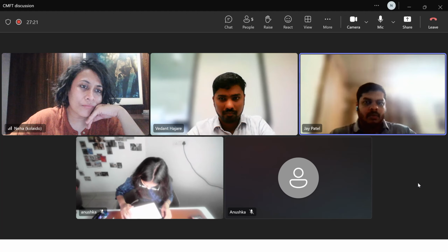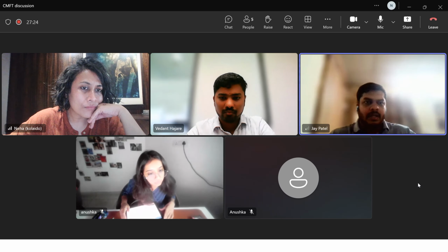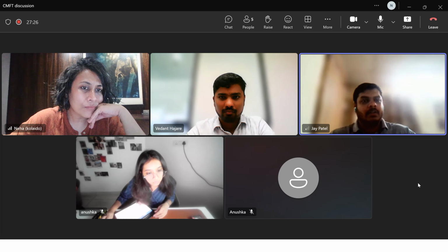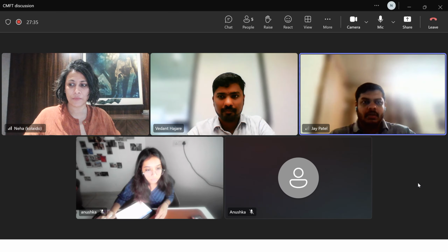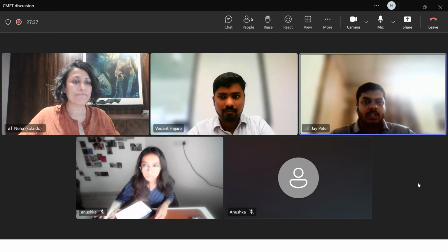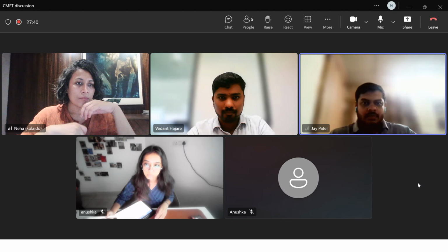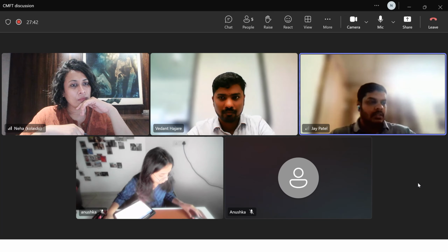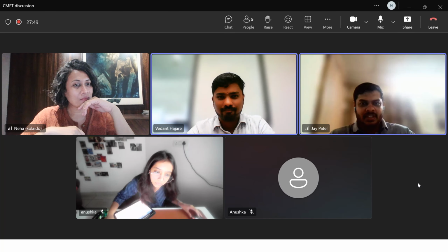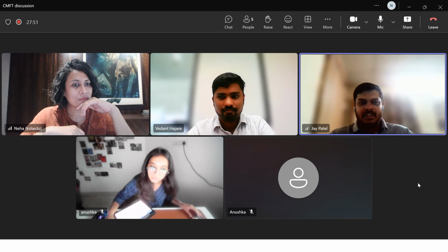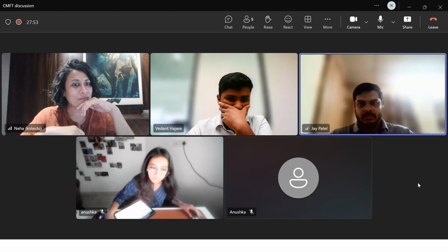Raw white fiber from the market, and then we dye it after the fiber is made, in a designated color. This is the option right now I have to select for our work, because in this case we can work in a small quantity, like 50 or 100 kg. But there is a catch: this after-dyed fiber doesn't feel the same as an inherent dyed fiber. There is some drawback, but we can at least start work on that.